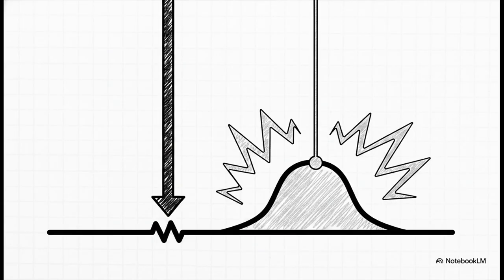Now, because of this ground impedance, which we'll call ZG, something really interesting happens. High currents flowing through shared return paths actually create a voltage lift. It's just basic Ohm's law, right? Voltage equals impedance times current. So imagine a heavy current running through the exact same ground path as a super-sensitive sensor. That ground potential literally rises. The sensor, which is referencing that exact point, mistakenly perceives that lifted ground voltage as noise in its signal. It's not some external interference beaming in, it's entirely self-inflicted noise simply because the ground itself moved.